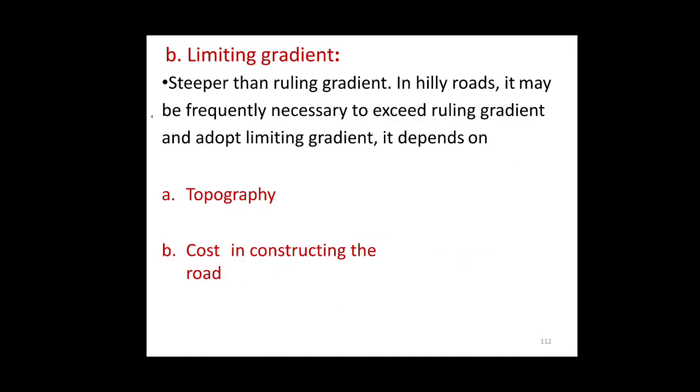So wherever the topography of the place compels adopting steeper gradients than the ruling gradients, limiting gradients are used in view of the enormous increase in the cost of construction of roads. With gentler gradients on a hilly road, it may be frequently necessary to exceed the ruling gradient and adopt the limiting gradient, but care should be taken to separate such stretches of steep gradients by providing either a level road or an easier grade.